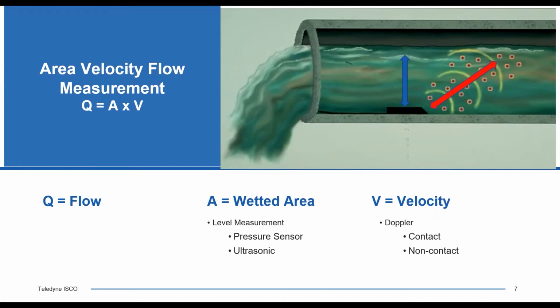On these types of sensors, what you can expect as far as accuracy is, if you're within roughly a 2 foot depth, 1.5 to 2 feet, you'll normally be in the 5 to 10% range if you have good hydraulics. What we found, though, is that as the flow gets deeper and deeper, the sensor will tend to underestimate the velocity because it is reading toward the lower part of the flow. With peak velocity, as the water goes up, the faster velocity will follow closer to the surface. That's the reason you may underestimate some of the velocity.